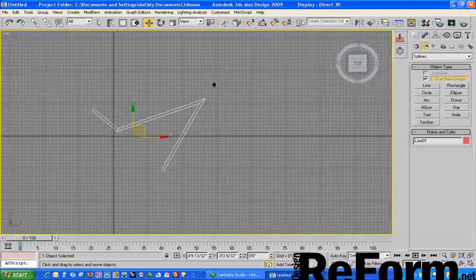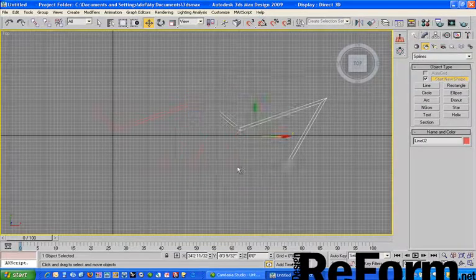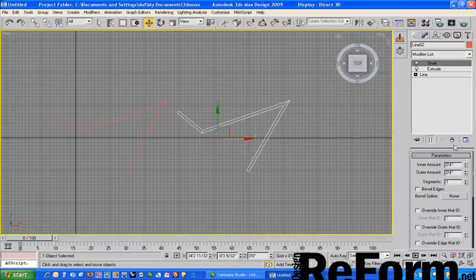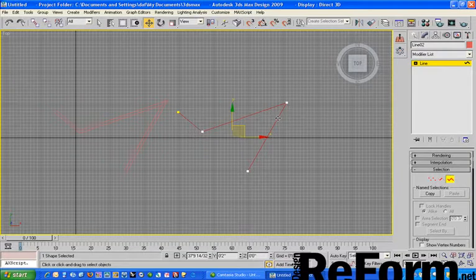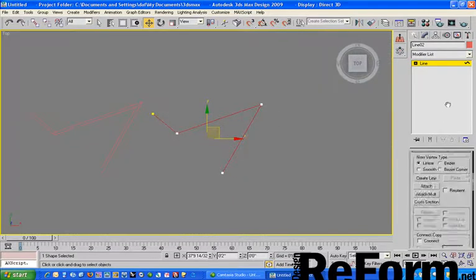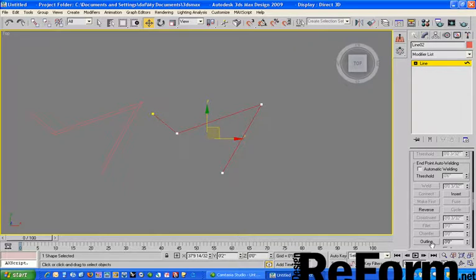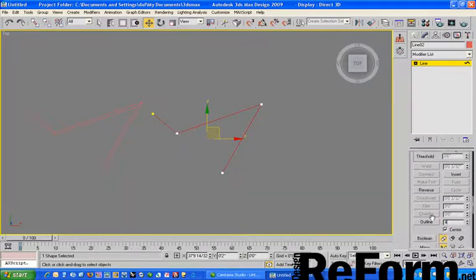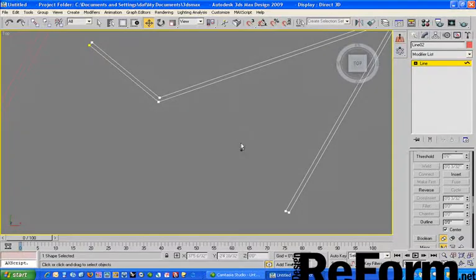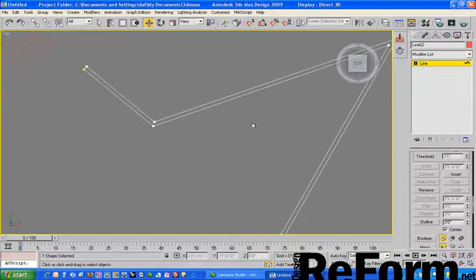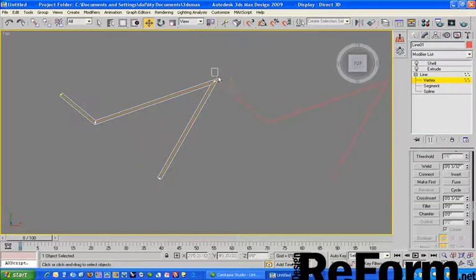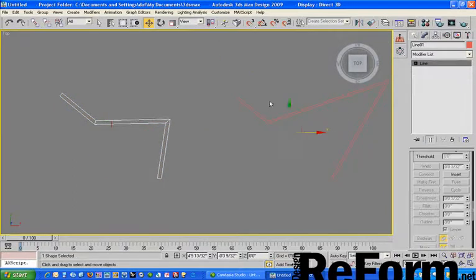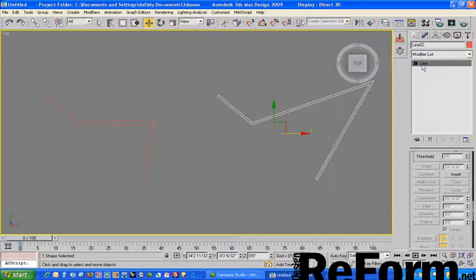And also one of the things I like to do is show the old way to achieve this effect. So if I go back to the line, get rid of these, what originally we would have done is gone to the spline level, turn off our grids by hitting G, and done an outline. And in this case it was center, and we'll do 4 inches. So that's how we would have done that before, but we really would have lost any type of associative properties we had, where now we can go back down to the original vertex and update this and our lines stay parallel, where with this one, and just to note, it was 4 inches total, didn't do 4 inches in each side.